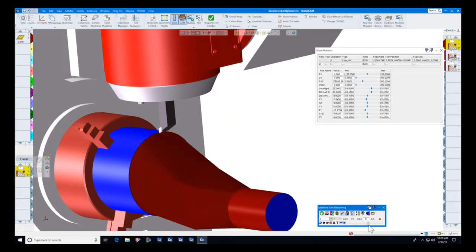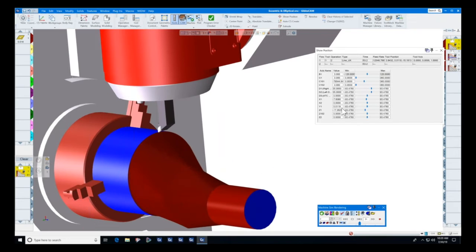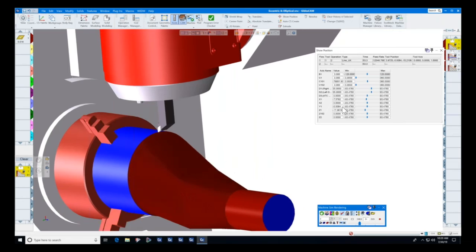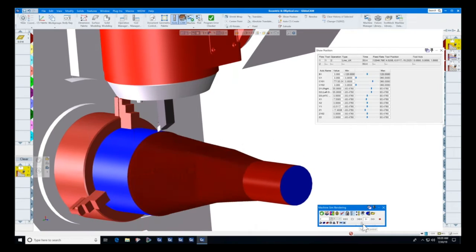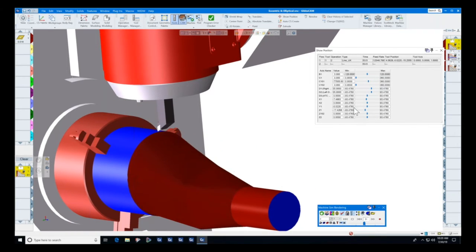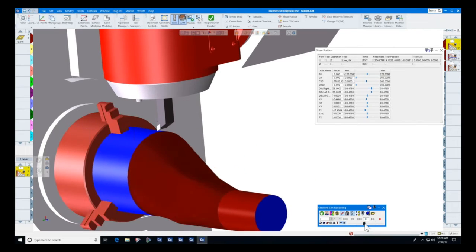Now we've transitioned fully to round. The y-axis is now settled down. We're only about 20 thousandths, 11 thousandths, 20 thousandths, and we're almost there to a fully concentric tool path. And when the y gets to 0, we're on a concentric tool path, and off we go.